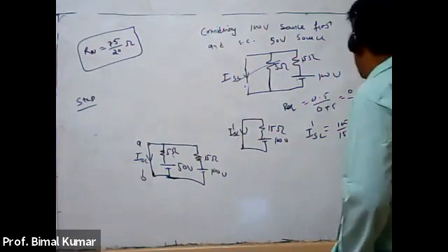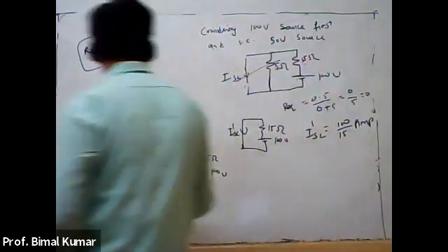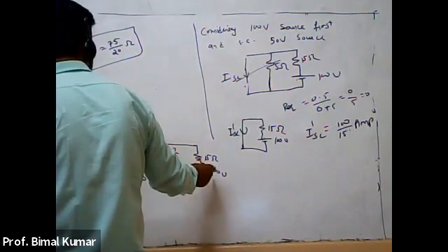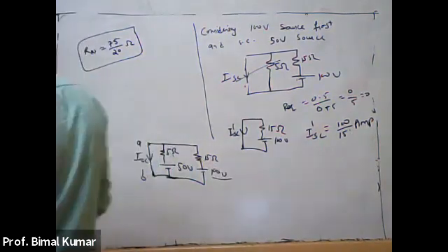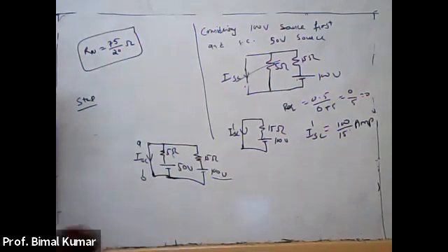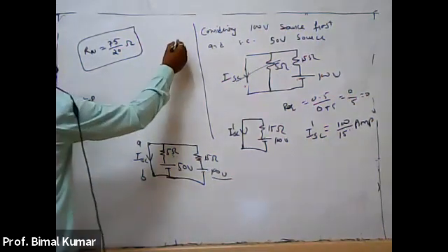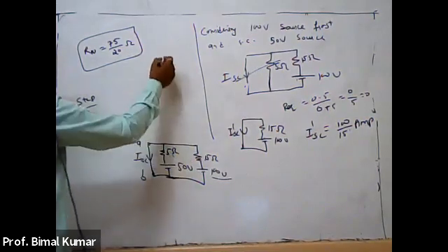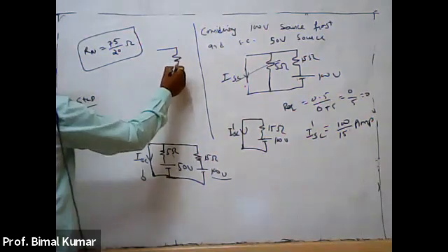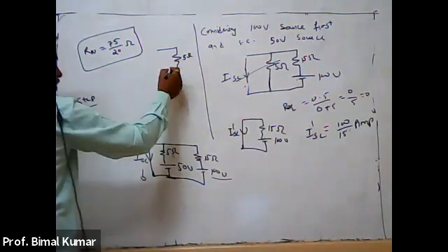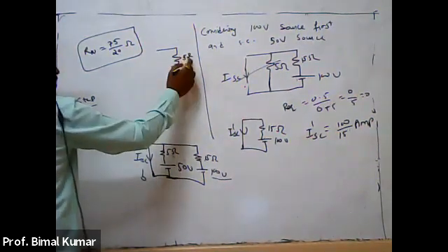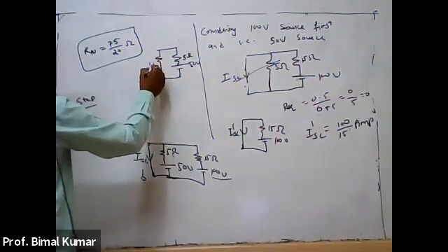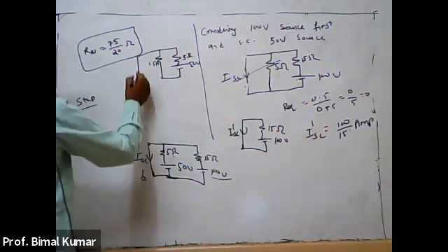Ampere. Now consider the second source. I'm just drawing it here. That means now I am going to apply short circuit across the 100-volt source. So this will become, these two branches may be interchanged in drawing, right? So here this will be 5 ohm and 50 volt, right? And this will be your 15 ohm resistance.